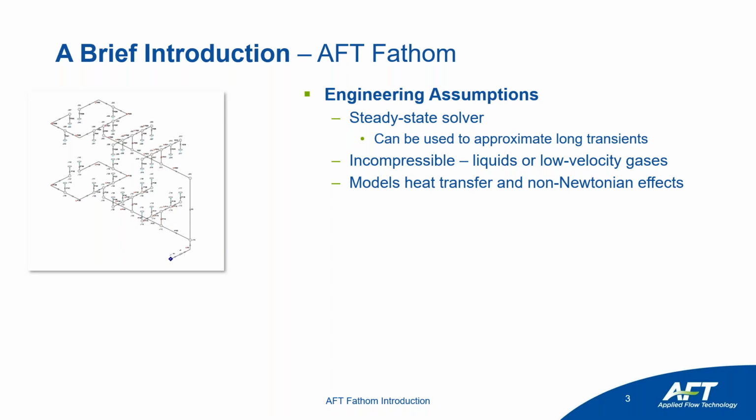The AFT Fathom solver is for incompressible flow. Most typically, that's going to be liquids, where the density of the fluid does not change dramatically with pressure. You can also apply this incompressible assumption to low velocity gases. As your velocities increase with gases, or you want to capture compressibility effects, how the density of your gas changes as it flows through your system, you instead want to look at our complementary product, AFT Aero, which we too will touch on later in the presentation.